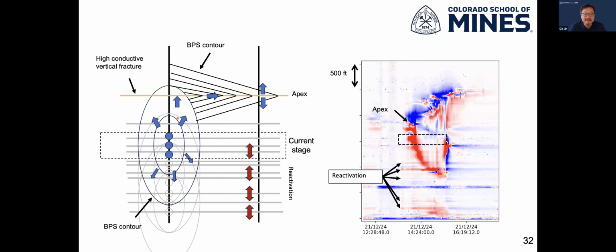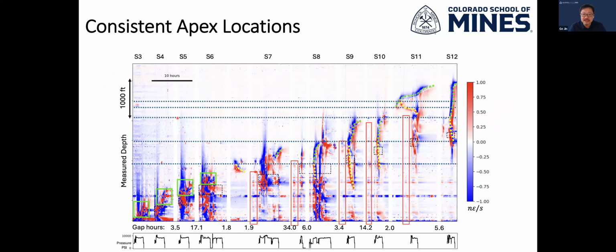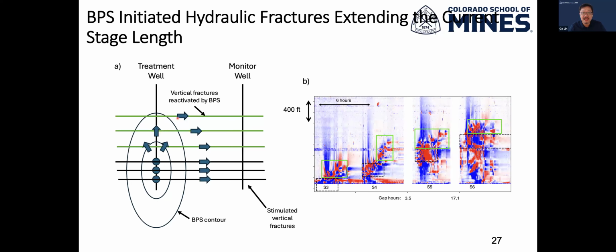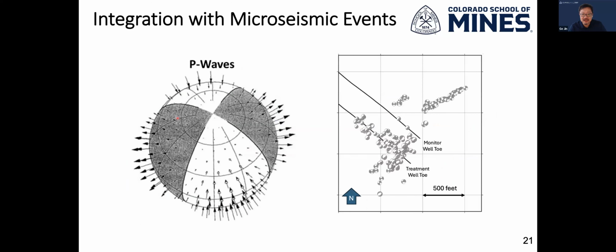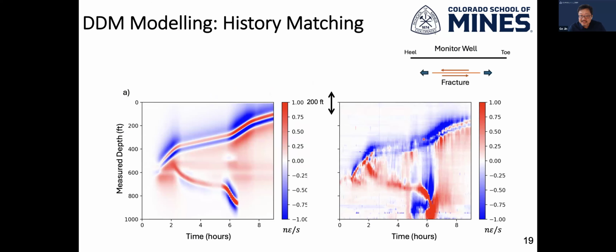That's an interesting comment. And actually, from the strain data, I didn't really show that. But let me go back to this. If you're running the geomechanical model, you can place this fracture at different depths and distances along your monitor well. You will see that if you put it further and further away, the spatial extent of the strain signal and also the pattern will change a little bit as well. So the spatial span will change as you move this fracture further and further away.